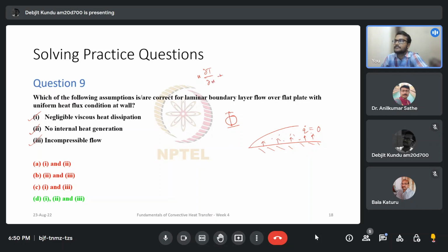Q dot E dot x plus V dot E dot y equal to dp dt term plus the material derivative, plus this temperature diffusion term, plus there was this viscous dissipation term. There was some factor in front of it, I don't properly recall, I'm sorry for that. But what happens is this is the heat generated due to viscosity.